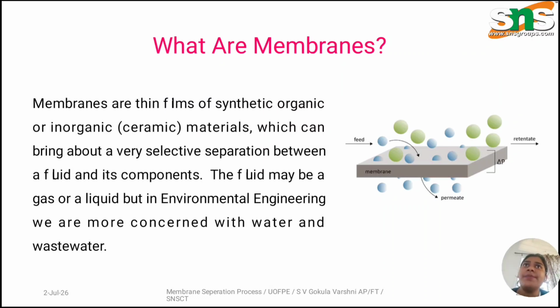You can compare a membrane to a kitchen sieve. When we sieve flour, only the fine particles pass through while larger particles remain behind. Similarly, a membrane selectively separates molecules. In food engineering, membranes are widely used because they do not require phase change such as evaporation. This makes the process energy efficient and suitable for heat sensitive food.